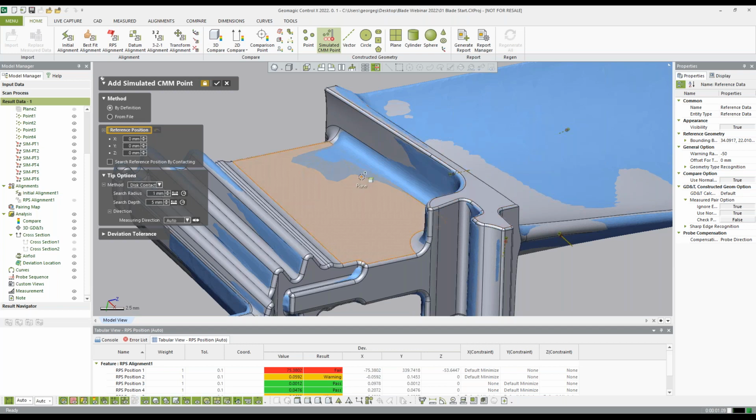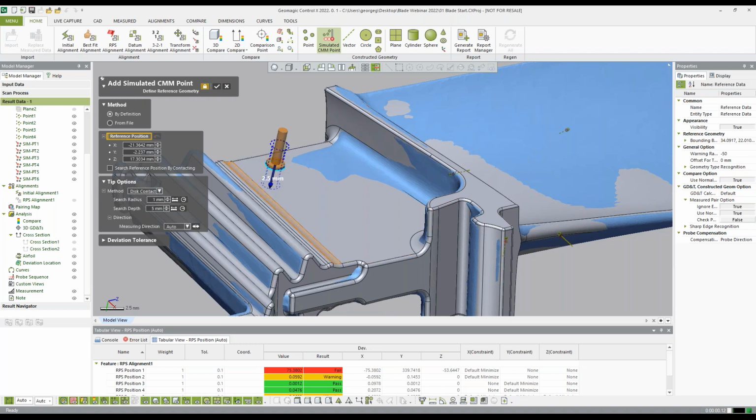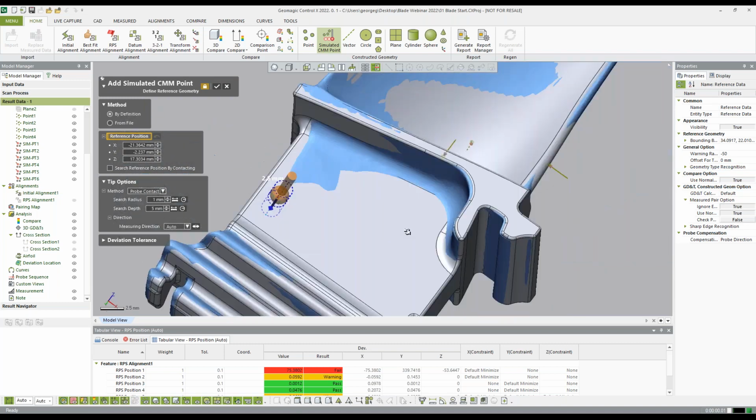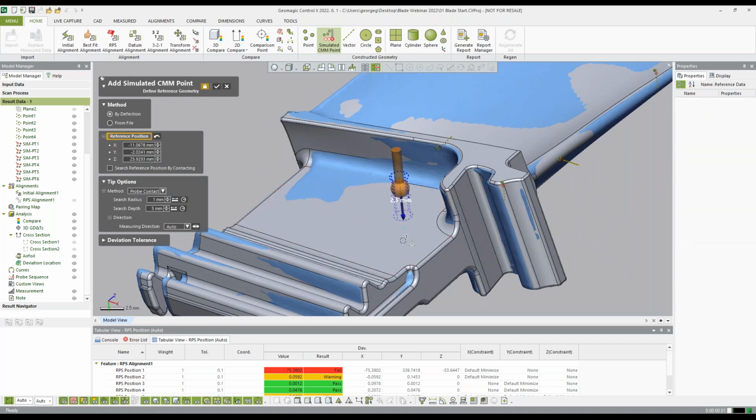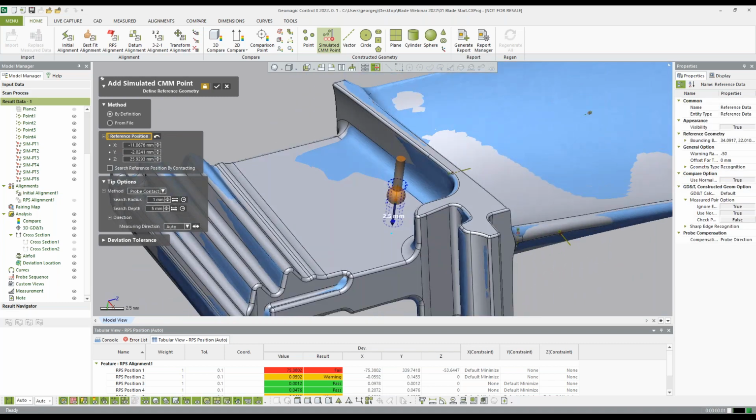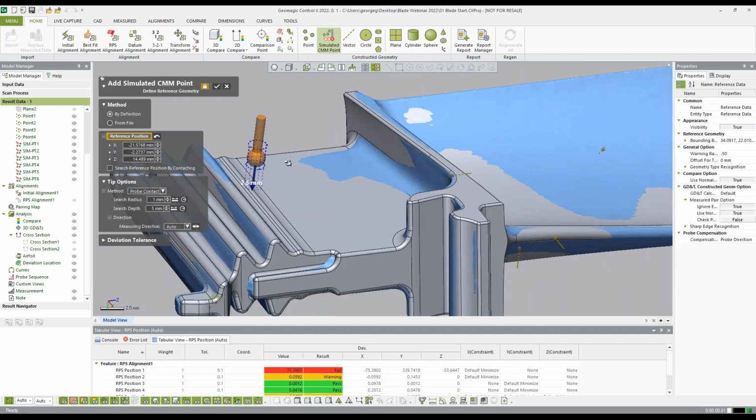But now that we have 3D scan data, there may be a few thousand points describing that plane, right? So we created this idea where you can virtually probe the surface of the part. So you see here, we can create these virtual probe locations. And then I can select these virtual probe locations, and then I can create geometry out of those.